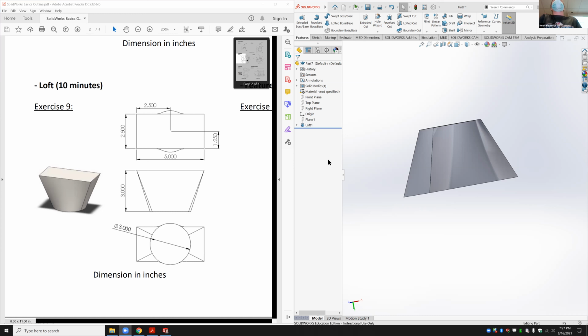Yeah, I just got the rectangle. Okay, so I just need to lock it. I can turn off the plane. Click on it, and then there's an eyeball. Click that to hide. Oh, you'll need to be outside. Go ahead, click that. There you go. Now you can exit the sketch. Oh yeah, you can also do it.